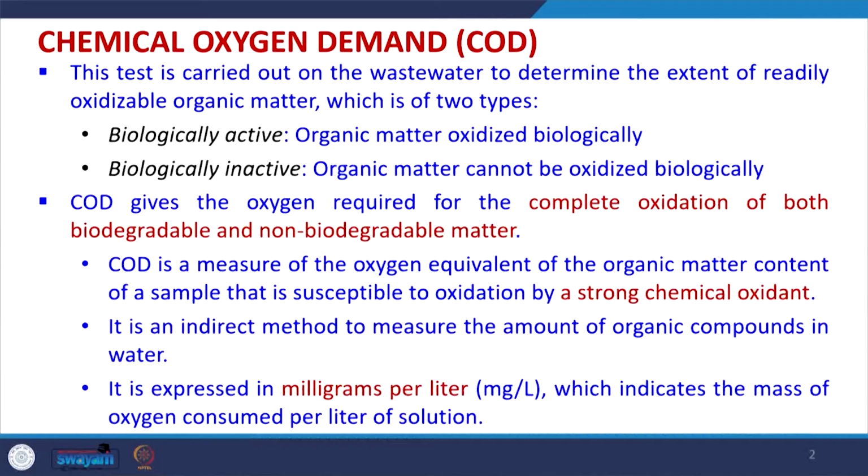are present in the water. But it is possible that the organics present in the water may not be easily degradable. They are called recalcitrant organic matter and they cannot be oxidized biologically. So, organic matter present in any water or wastewater may be biologically active or biologically inactive.